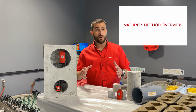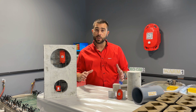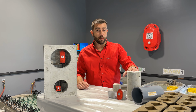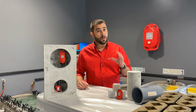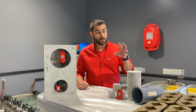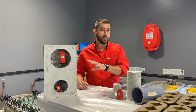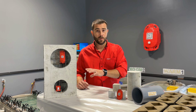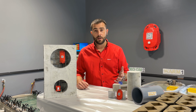You're probably familiar with concrete. It's one of the world's most widely used building materials. And traditionally, we've used cylinders and their break data to help us understand the strength of concrete. Now the only challenge there is the temperature and the strength development that's happening here isn't necessarily the same as on your project. Now the maturity method is another tool or resource that we can use to help us here.